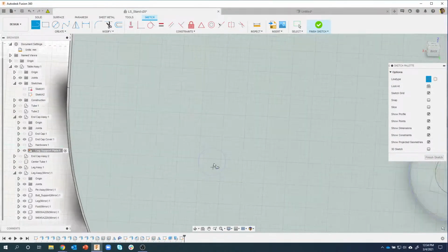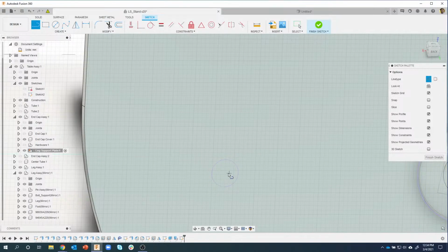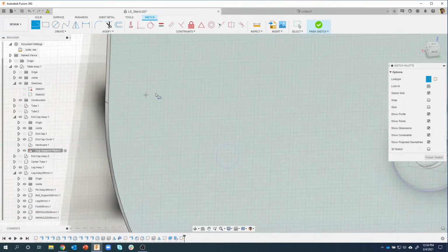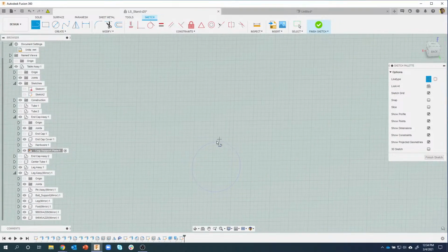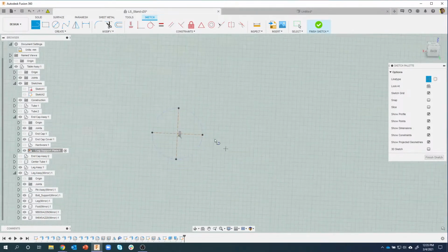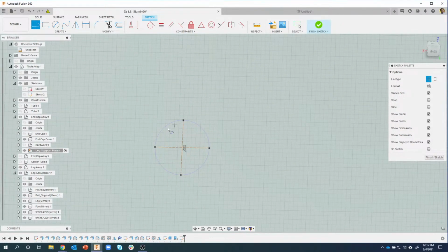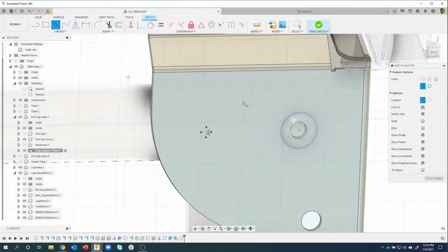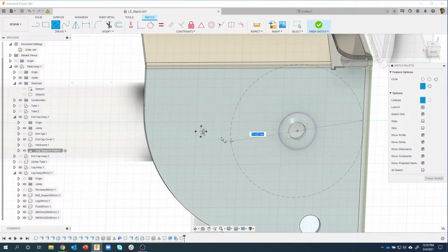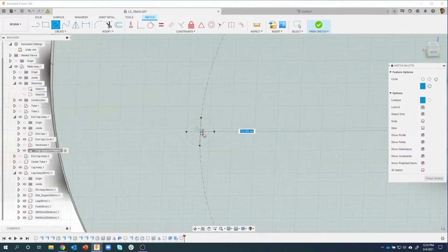Huh, that is odd. I thought it would project a center point for me, but it's not. So I can kind of get around that using center lines here. So for example, I can draw a line like so, and a line like this that would go across, right? So it's catching those quadrants. So now I have a point that I can get to. So now I should be able to do my circle. So I'll go from there to that point there.